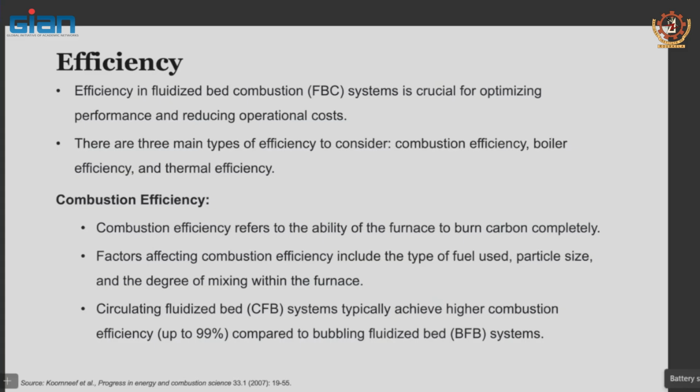I'm assuming that you're able to see me when I show you something. So when you have this tube, this is a heat transfer surface. Water or low pressure steam is going in and coming out as steam or high pressure steam. When this is in a very dirty environment, you have a lot of ash particles at a higher temperature than the tube, coming and hitting the surface. After a while, you have slag formation or condensation of hydrocarbons that form soot over this.